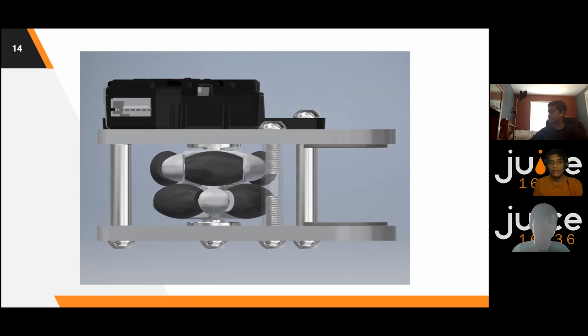The biggest surprise that a robot gave? That would actually probably be it. When one of our wheels just stopped working, it was really confusing when we saw it happen, because our Auton worked almost perfectly fine, but our drivers were almost completely unable to control the robot. We found out the only reason our Auton worked was because of our PID loops. So PID is very powerful if you can implement it.